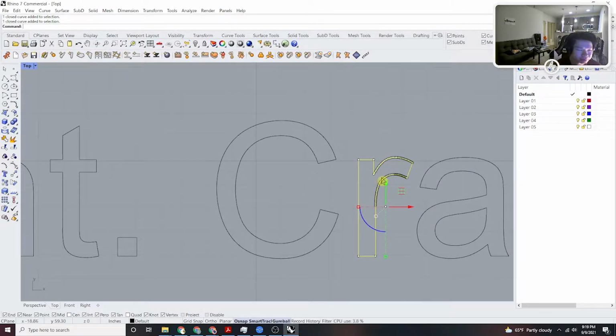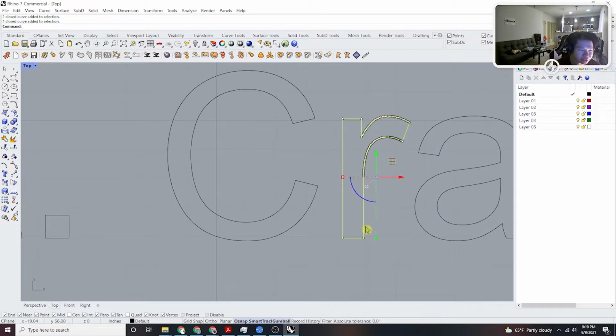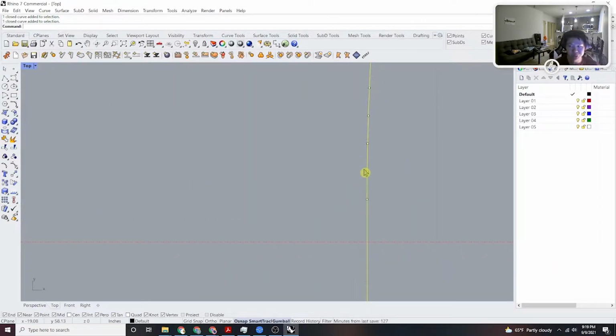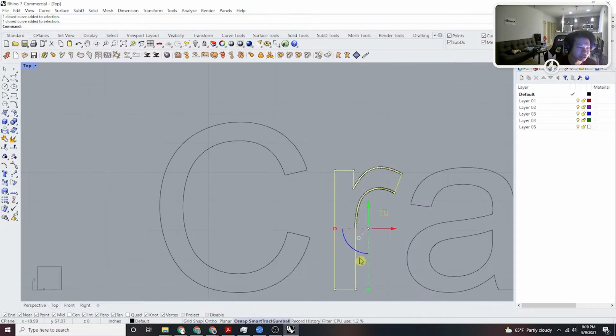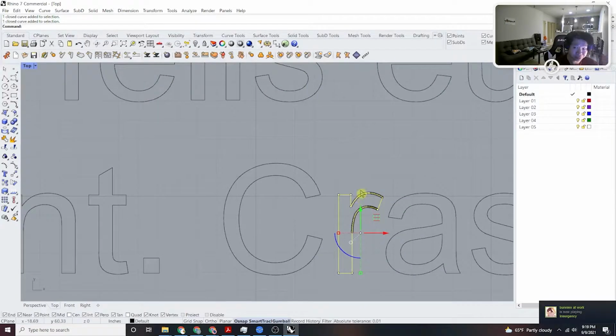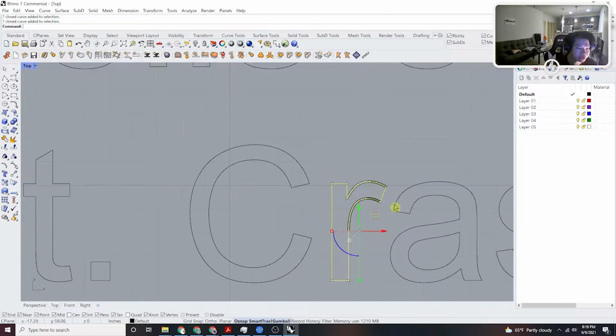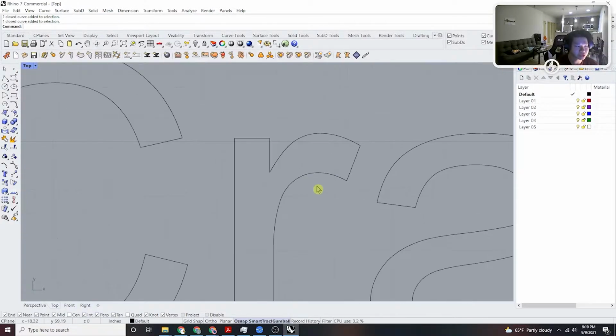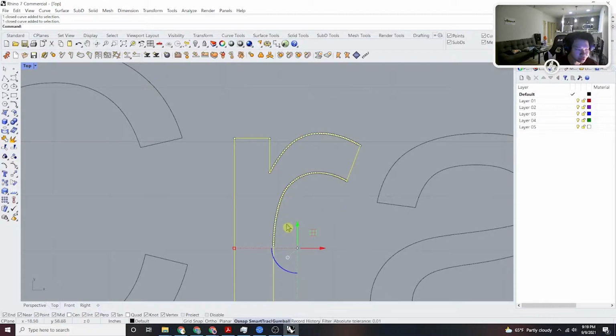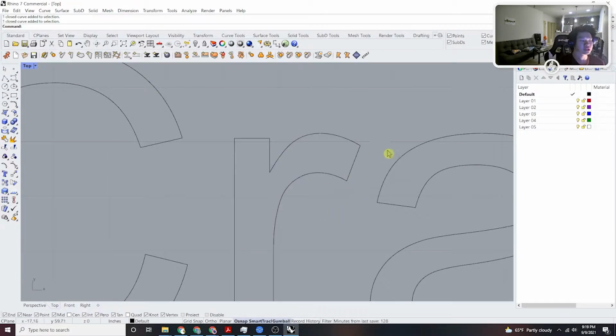So I was like, okay, I could do that, because if I filter it based off these lengths, all these segments are super tiny. That's what we're trying to get rid of. So if I can capture these larger segments and keep those, I don't have to rework them. I just have to modify only these arc pieces here, here, here, here, here, and then it'll be good. And then I just remake these arc pieces with Interpolate Curve and then join them. And then it should be good, right? So that's exactly what I tried to do.